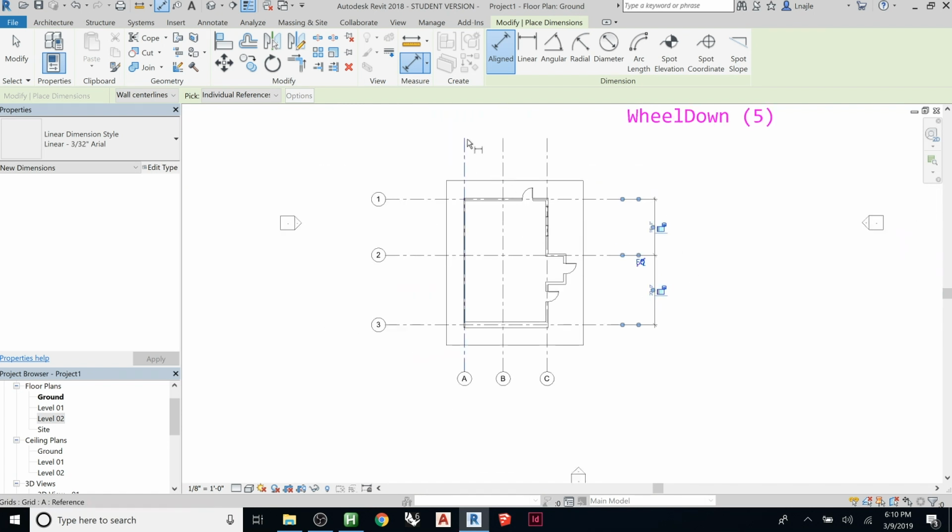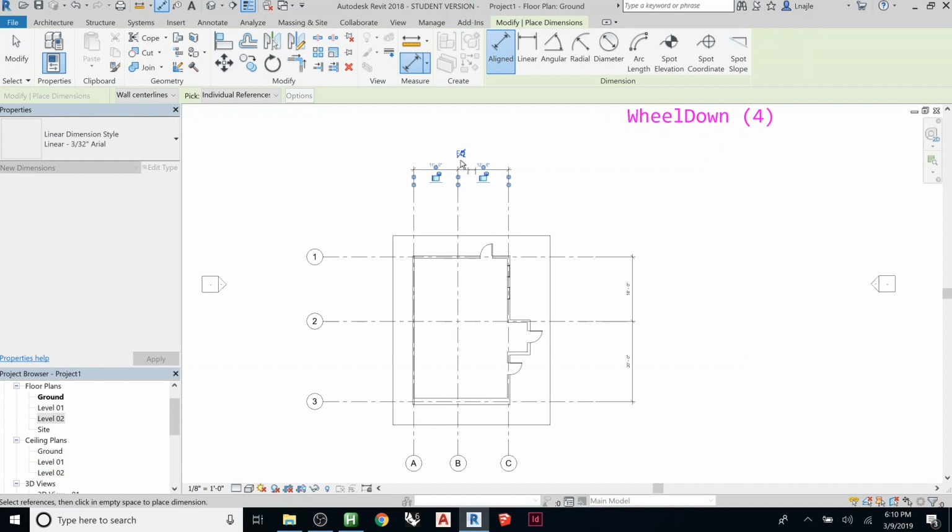If I go here now and say boom, boom, boom, we have 11 and 12'6" not equal. If I did want them equal, double click there or just single click on EQ, you'll see these change to EQ, EQ, and it's moved them so that they're centered. You can do this with, let's say we want to add more grid lines.